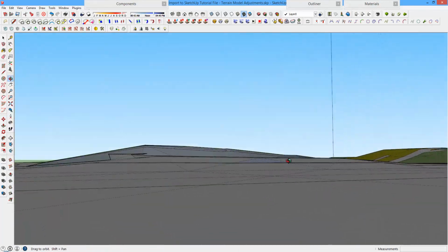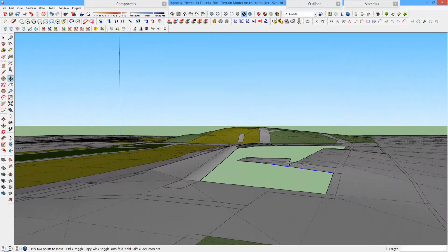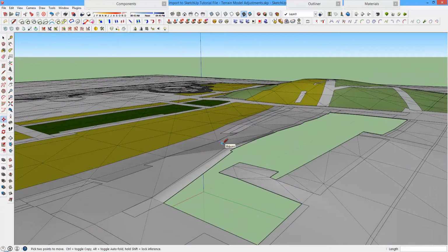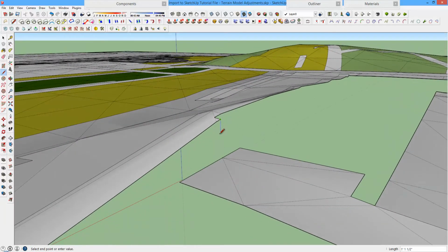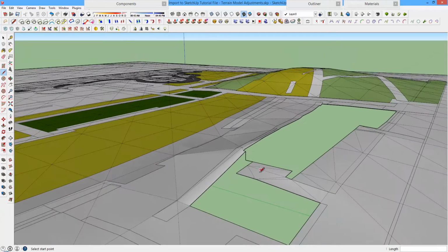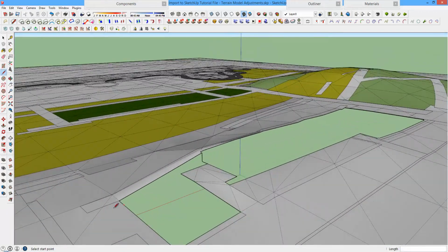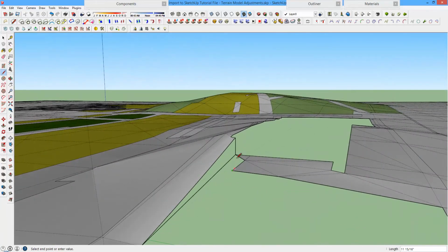Okay, so now I've got that kind of reshaped the way I want it. Slopes up, still a little bit of slope away from the building. It's kind of level around the front here. This slopes down. So now to rebuild this is pretty straightforward. So the first thing I'm going to do is draw a line straight down from this corner that was the existing corner and tap into that line and then connect to that line. So that tells me kind of where that edge is going to be. And then I can draw a line from this corner up to there to here. Can start closing that in from here to here.